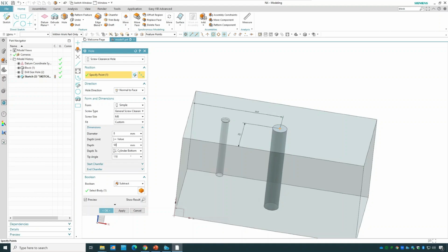You need to, because basically the kind of clearance you put, it will impact the final tolerance analysis, because it depends on how much pressure, as a result of the screwing, the screw will impact up to the rest of the body of the block that we have here. So this is all different kind of customization you would be able to have there.